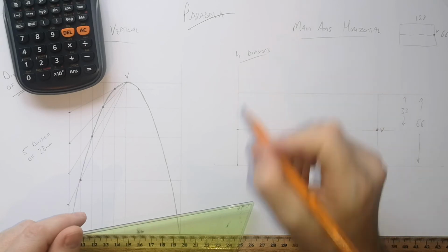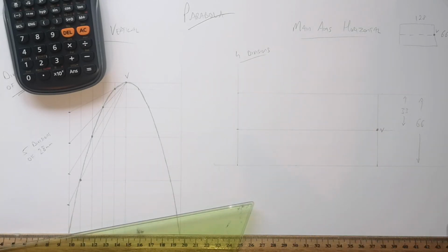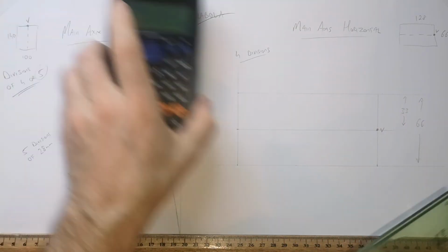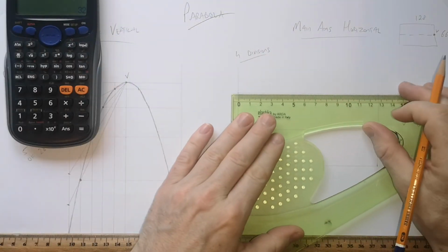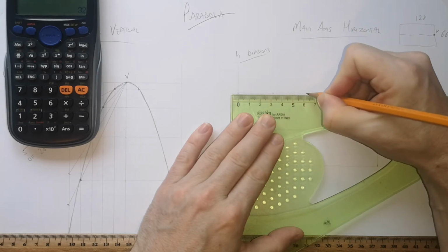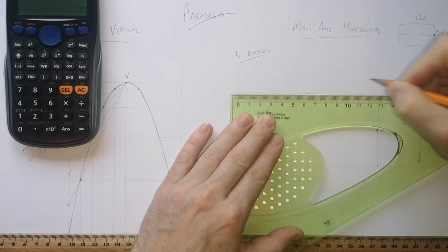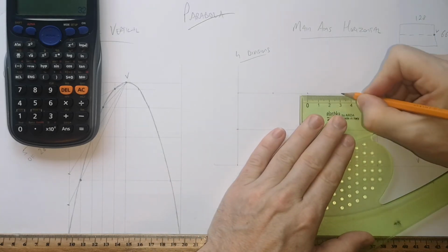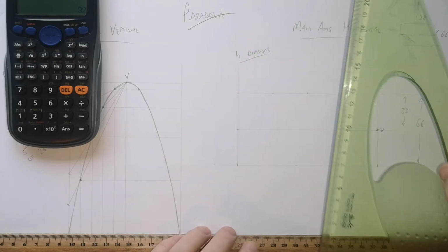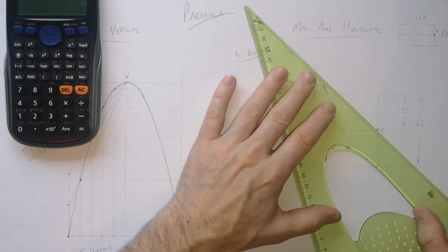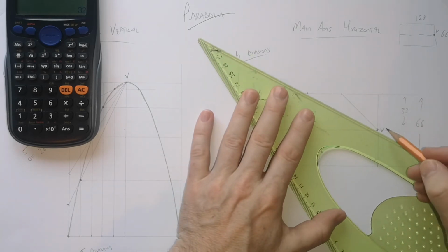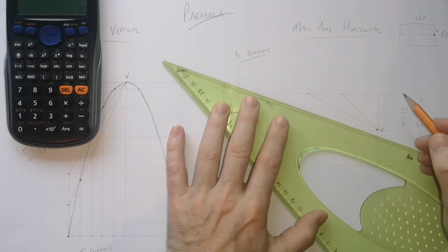No point in making extra work for ourselves. 3 doesn't give you enough information. By 6 divisions, you're just making more work. So we'll divide this one up nice and easy. That was 32 millimeters. So there we go, 32 and 64. And we'll just reset again. 32 and a quick check, yes, 64. So that's going to give us these divisions. Remember, these lines are going to go diagonally to the vertex.